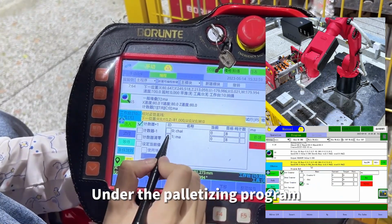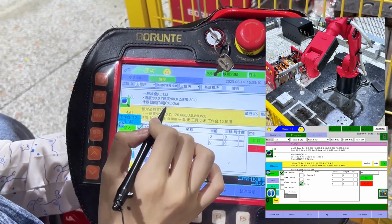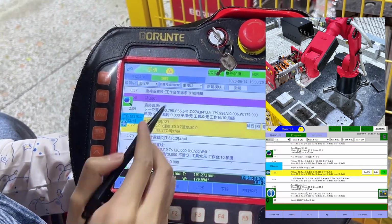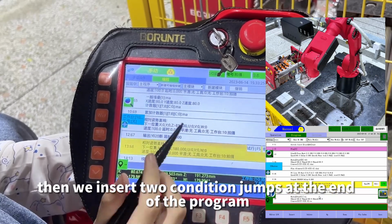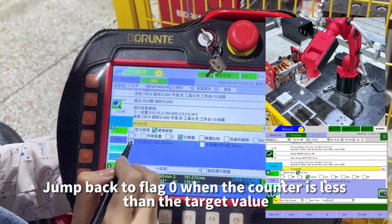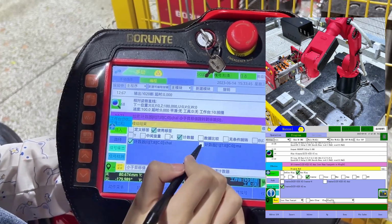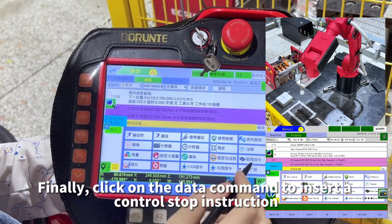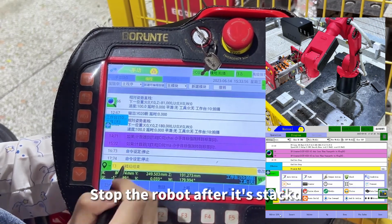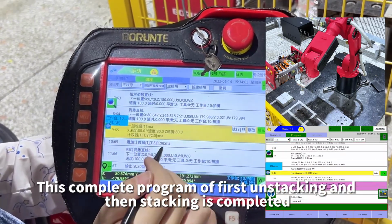Under the palletizing program, insert the corresponding set counter. Then we insert condition jumps at the end of the program. Jump back to flag 0 when the counter is less than the target value. Finally, click on the data command to insert a control stop instruction. Stop the robot after its stacking. This complete program of first unstacking and then stacking is completed.